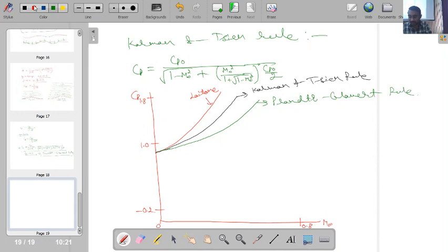So if you now plot over this, the experimental data points are something like this. One is here, then here, then here, so like this. So you can see that Karman and Tsien is mostly fitting in the entire region, whereas Laitone and Prandtl are actually fitting in the very initial portion when the situation is very close to the incompressible flow situation.